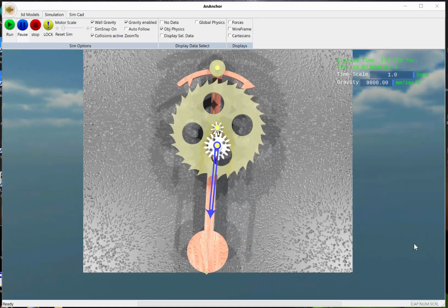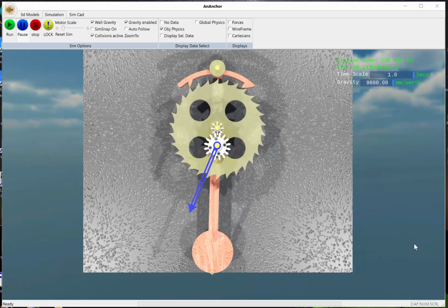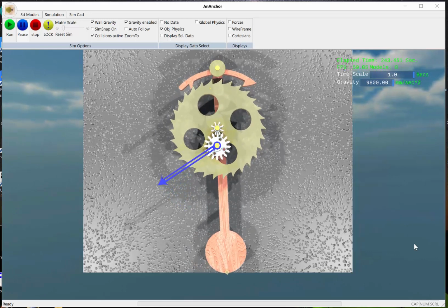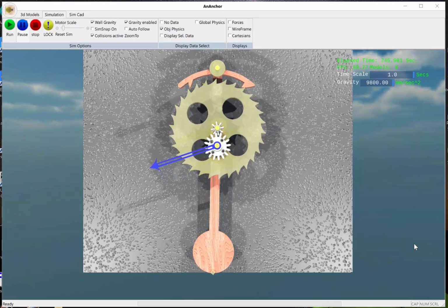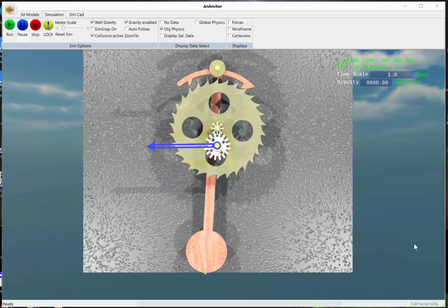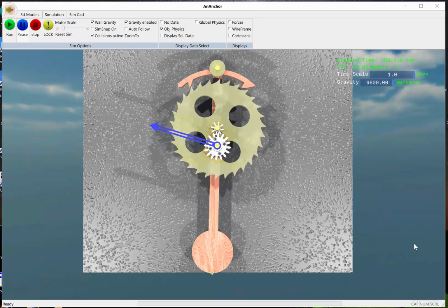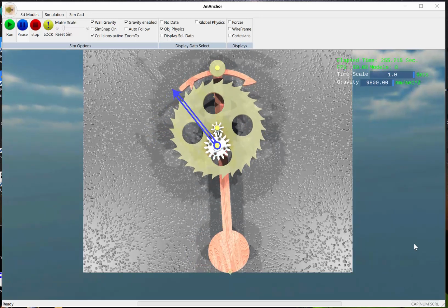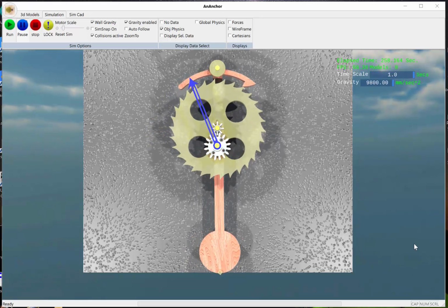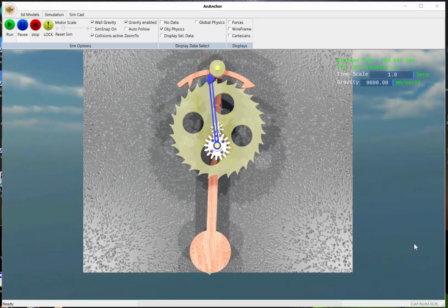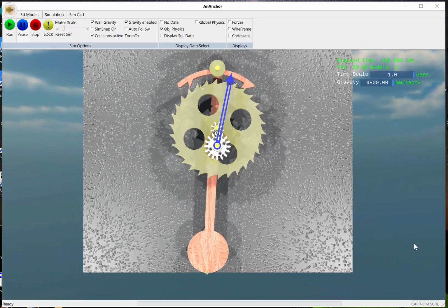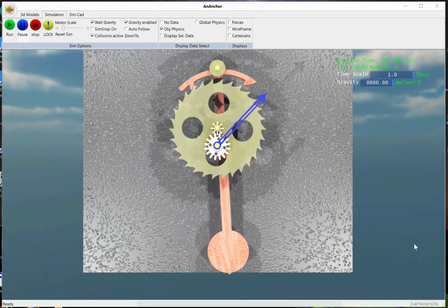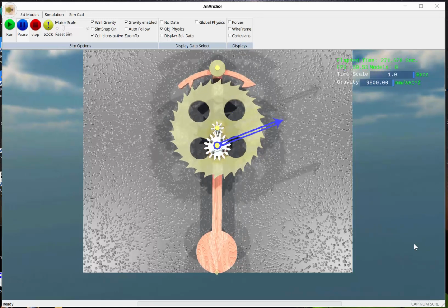We're soon going to be into the 400th anniversary or so of the invention of the anchor, and it superseded the verge escapement, which was found to be too inaccurate. The anchor escapement is much more accurate, and it was about the time of the invention of the anchor that they discovered that the less a pendulum swings, the more accurate the timepiece. And so the anchor was their first replacement for the verge, and would a few years later be replaced by a deadbeat, which, although it's slightly more efficient and accurate, is also somewhat more finicky to get running.